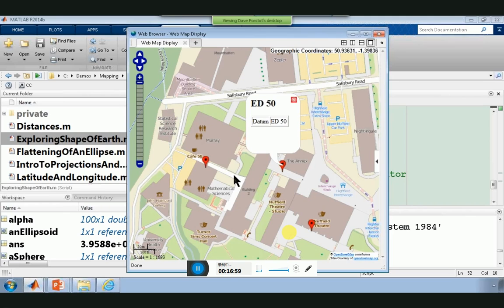Now, when you have datum that have evolved over time but designed for the same region, the differences are going to be very, very small. However, if we use maybe the North American datum, any one of its manifestations, this may have even more error over here because that was designed for North America. These 3 are all pretty close in terms of geography, but in terms of distances, we're going to see in a few moments that given the scale here is 20 meters, these are 100 plus meters apart.